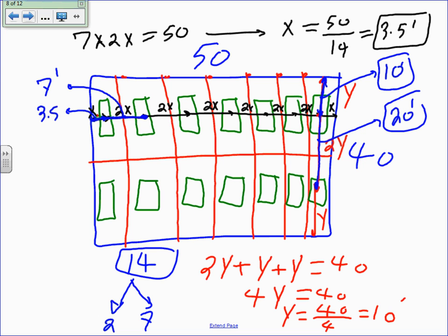What I'm doing, guys, is after I decide how many fixtures I need in an area, I need to lay out my fixtures in a way that gets me the best lighting distribution system. Best lighting distribution happens when your fixtures are equally distributed all over the space. How can I find that though? I need to give it to an electrician to install this. You can't just put it on a piece of paper here and say, well, do it. You need to do the calculation to find the orientation of each one of these fixtures, as well as the x and y for every fixture.